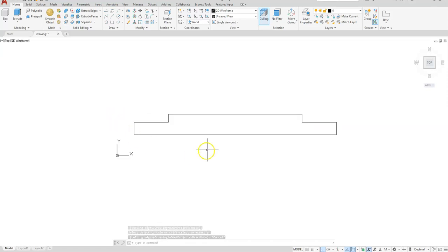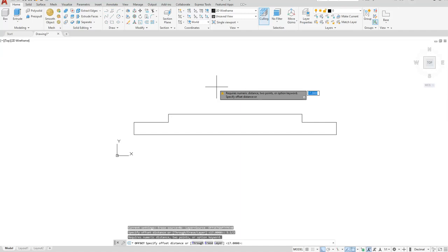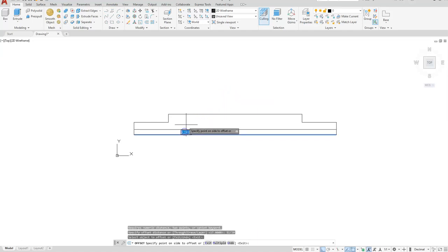So the next part is that I do have a grease diameter running through here for the grease filling to go through. So I'm going to go ahead and offset and create that circle located here. I'll use the offset command, and if you try to use the offset distance of 5.1 divided by 2, AutoCAD gives you an error. So I'm going to manipulate that a little bit. I'll use 51 divided by 20, and I'm just moving the decimal place on the numerator and the denominator, and that will allow me to offset that line the correct distance.